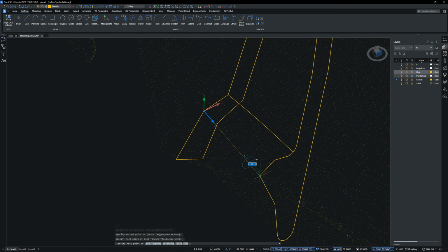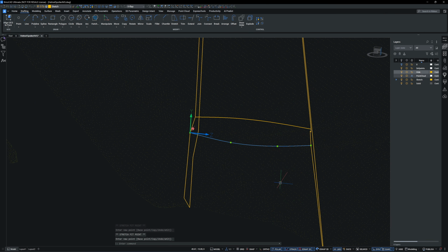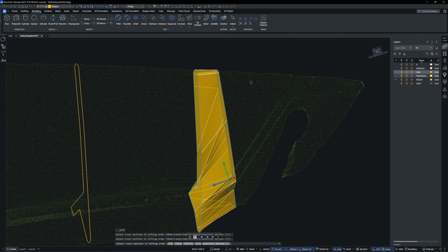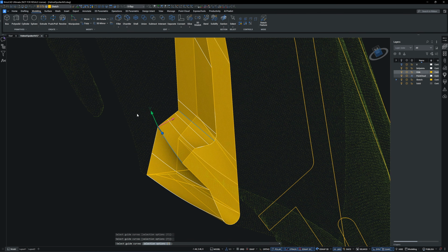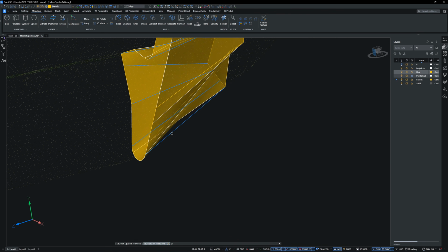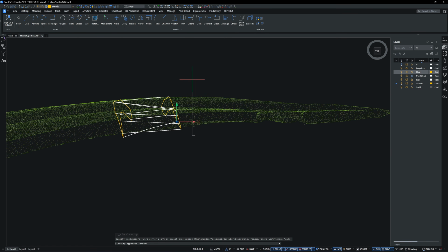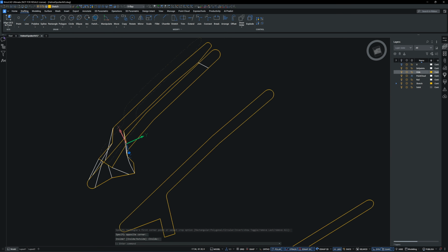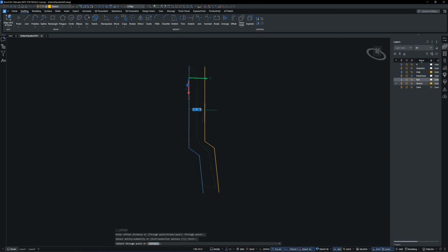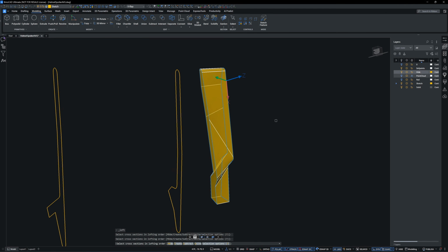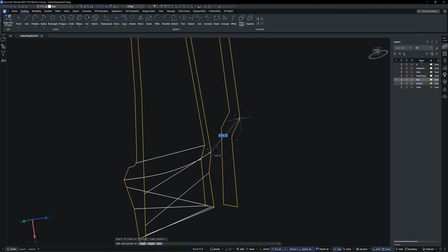The guide rail is a spline with 2 control points. You can create it easily by making the UCS Z-axis and drawing the spline along the polar tracking line. Here I'm only testing the loft profiles, not creating the final loft yet. I will generate them all at once after finishing all the sketches.